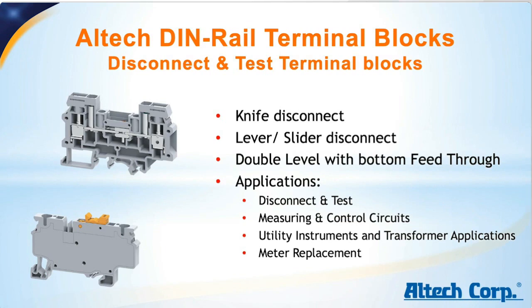The fuse terminal blocks are actually already one type of disconnect terminal block, but there is a different group of disconnect and test terminal blocks with which you can disconnect the circuit.